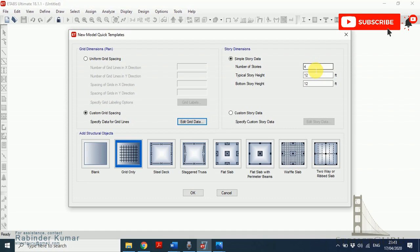The foundation is generally kept at 1 to 1.5 meter below the ground level. So let's suppose 4 feet or 5 feet below the ground level, our plinth level is 3 or 3.5 feet above the ground level, and our first floor level is 12 feet and the second floor level is 12 feet.